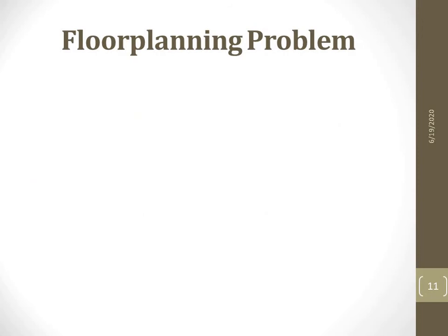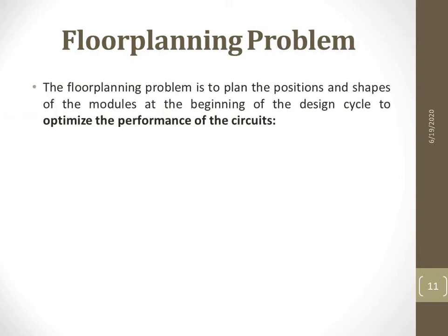What are the problems related to floor planning? Till now we have seen what the inputs for floor planning are. Now, what are the problems with floor planning? The floor planning problem is to plan the positions and shapes of the modules at the beginning of the design cycle to optimize the performance of the circuit. How can you optimize? By planning proper positions and shapes of the modules at the beginning of the design cycle itself.